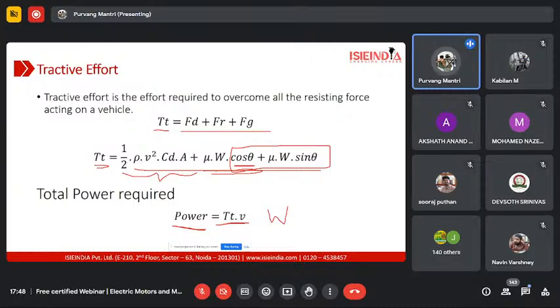If you want, you can also use a two-speed gearbox. Many electric sports cars like the Audi e-tron and Porsche Taycan use two-speed reduction gearboxes. In those cases, the first gear provides high torque, while the second gear provides high speed.